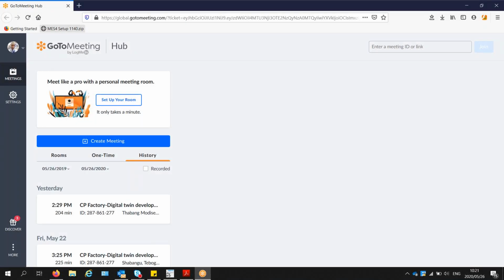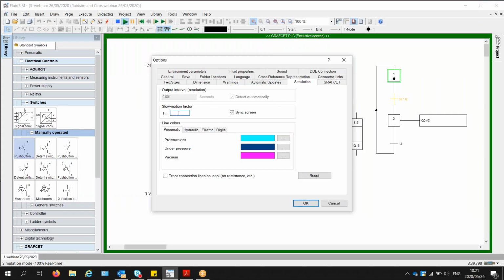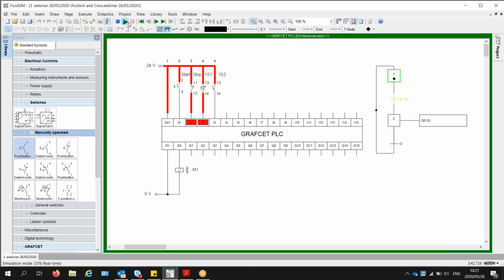So this is only for simple pieces of your circuitry that you can simulate from the PLC. But what the guys would have really liked is to import the complete program into Fluidsim, but unfortunately that's not possible. You've got to rebuild that whole GRAFCET, that sequential function chart, from scratch. That's it.